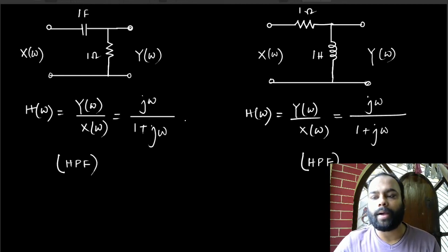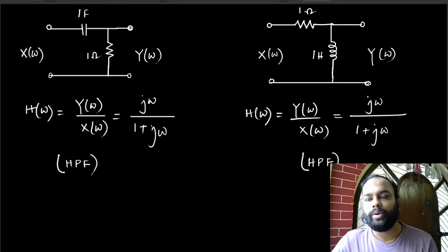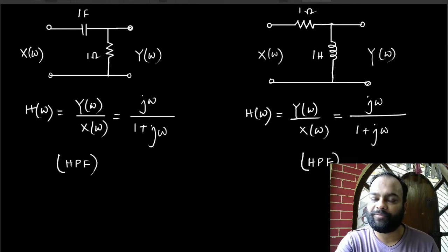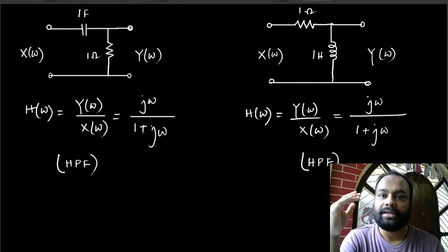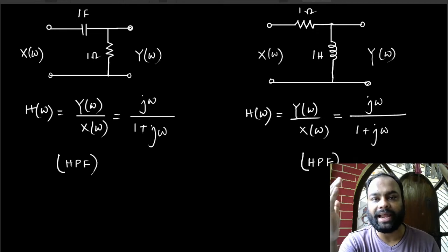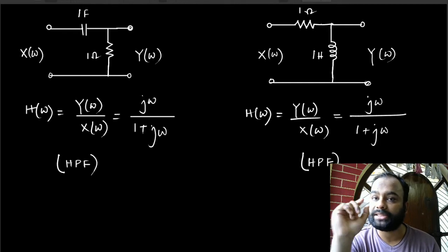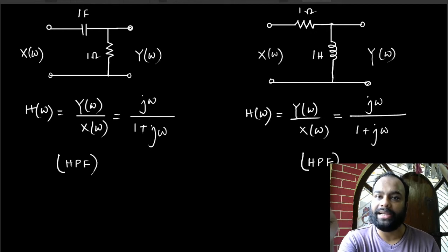But in an inductor, if we have an inductor with high enough inductance, you probably don't have an air core, you have some ferromagnetic core, right? An inductor is nothing but a coil wrapped around some ferromagnetic material. The ferromagnetic material doesn't have a linear BH curve, right? So with an inductor, the flux density will not always linearly increase with the magnetic field intensity. You might increase the current through the inductor, but the flux density will not always be proportional.